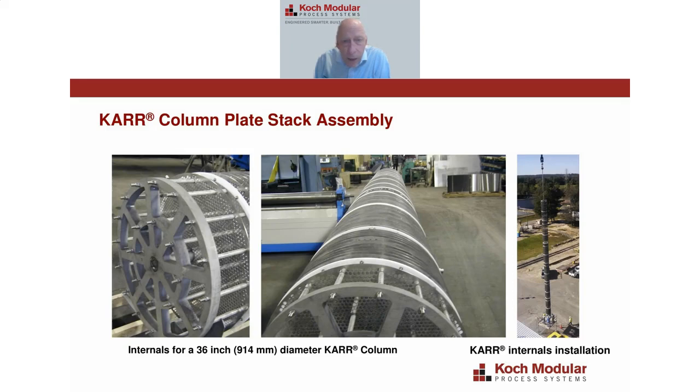55-60% open area. They're typically spaced 50 millimeters or 2 inches apart, although we will vary that depending on the mixing intensity we want throughout that column. Then we have these white edged baffle plates. Those are donut-shaped plates with an outer Teflon edge that's higher diameter than any other plate inside that column, so that when you slip this in the column and you reciprocate it, the only wall contact would ever be that little Teflon edge to the wall and not a metal to whatever metal or glass line or whatever you're making your column out of. And then we have these spider plates.